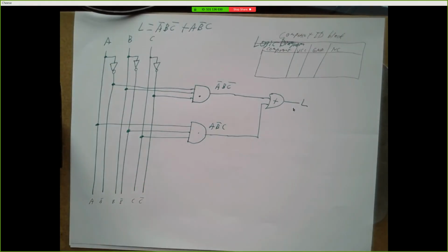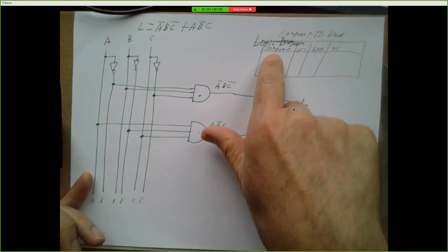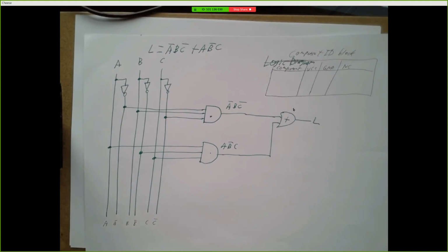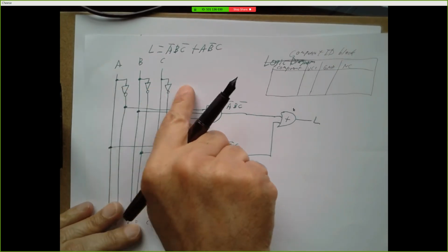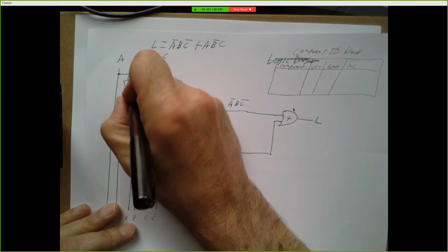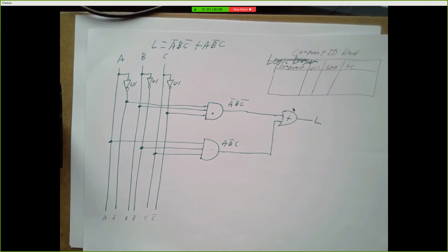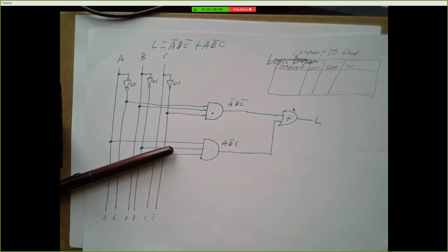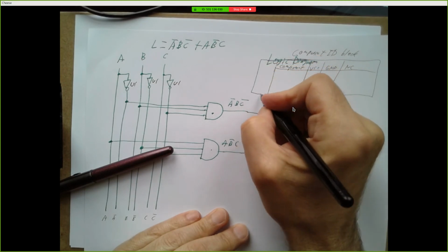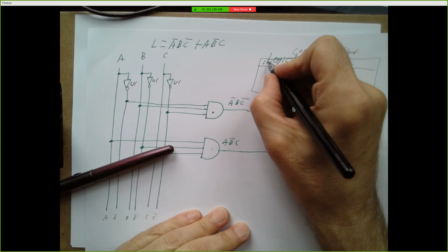And every time that we have a logic gate in here, we map it to some component up here. So for an inverter, we want a 74LS04. Well, we don't want to write 74LS04 over and over again, so we just name this something, for example, U1. And we have a column up here, which I'll just call ID or something.